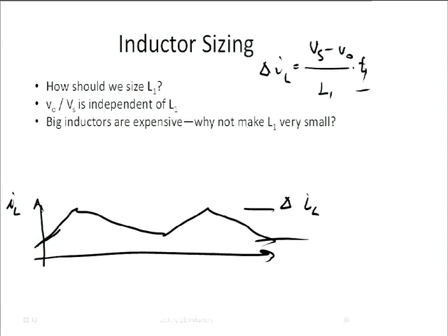And in fact, in Lab 5, you're going to build this thing, but then in order to make the lab a little bit simpler, we're actually not going to use a 555 timer. We're going to use the function generator, simply because that way we have to put fewer components onto a prototyping board, and there are fewer chances for things going wrong, and therefore there is a better chance for you finishing in 3 hours. Right? So we think about that when we design the labs.